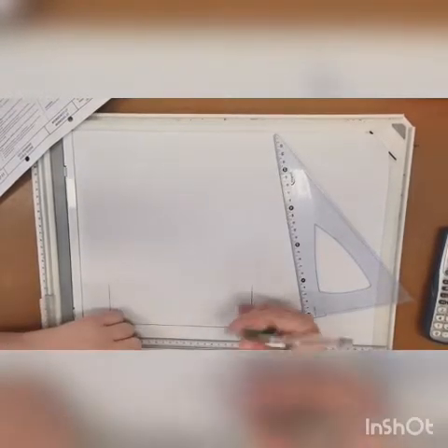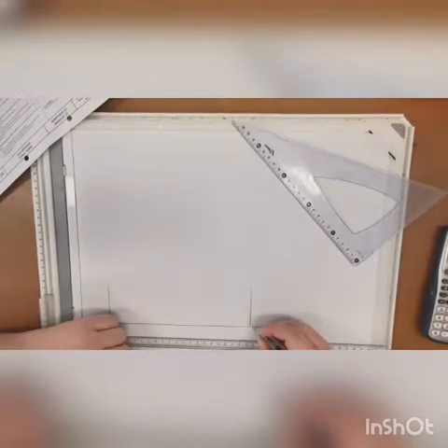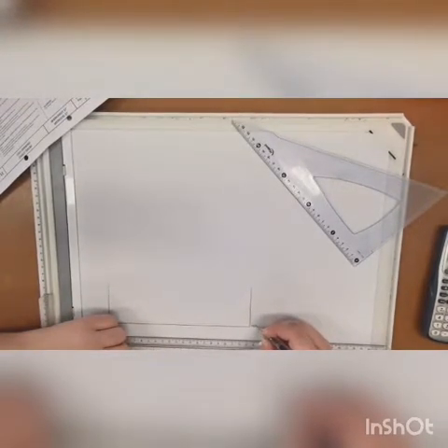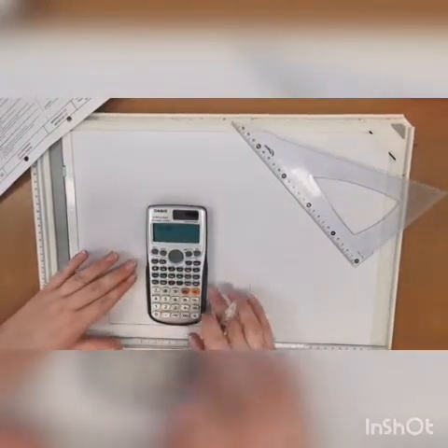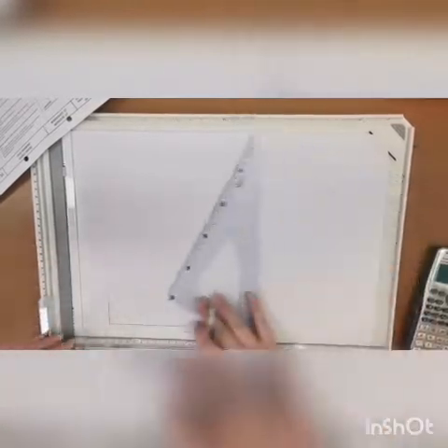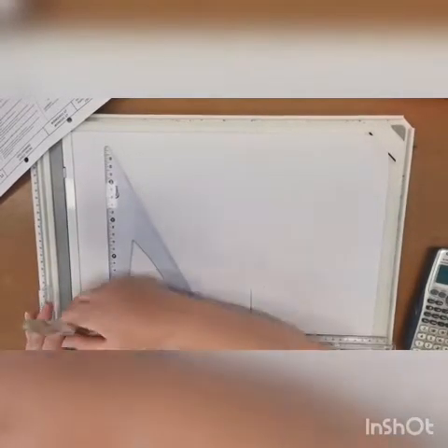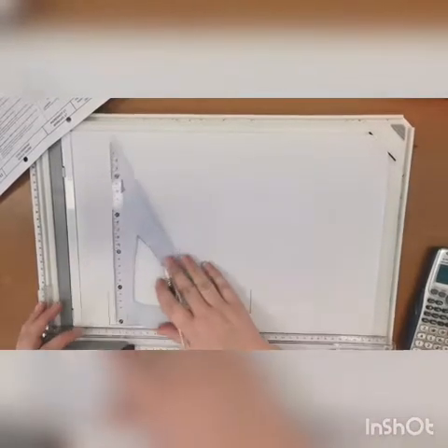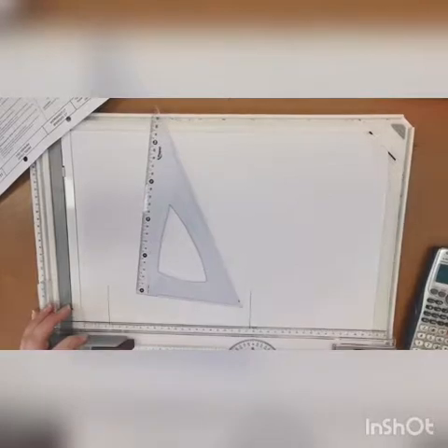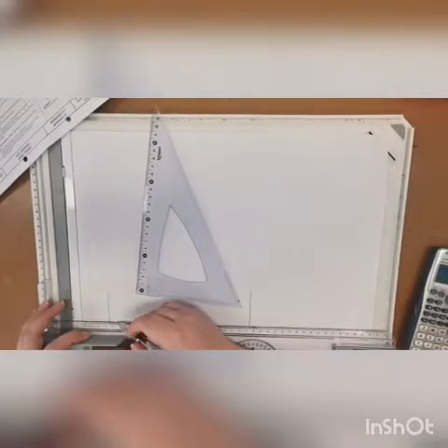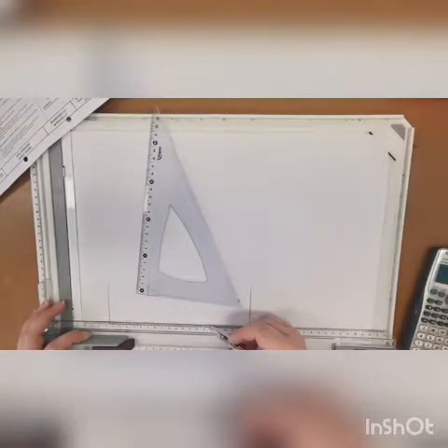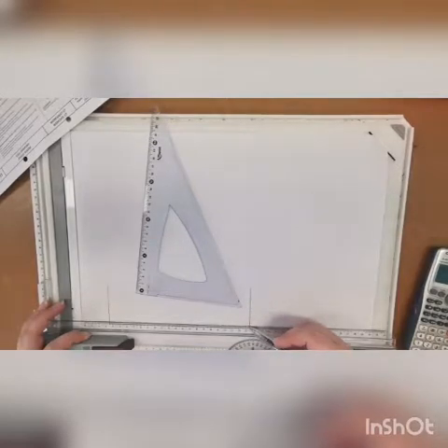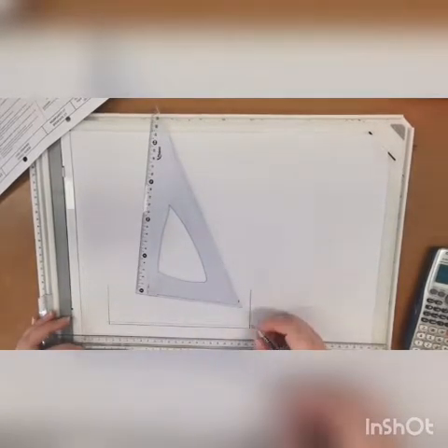Please don't forget labels. You will get marks for saying natural ground line. And I must put my finished floor level in, which is 170 divided by 50, which is our scale, 3.4. Your floor level gets done in this line type, the long, short, long, short. Alright, and we label finished floor level.